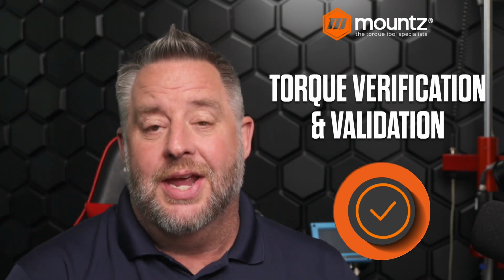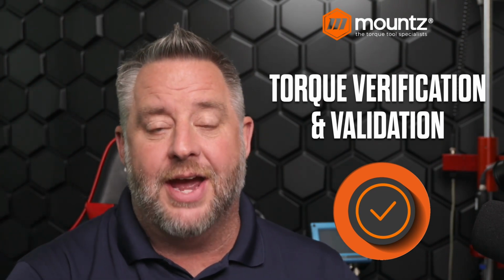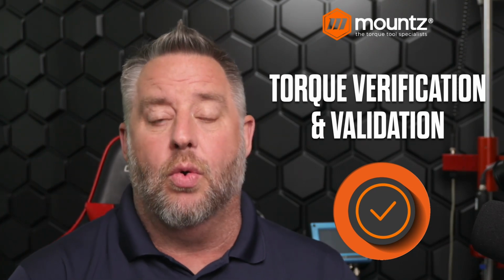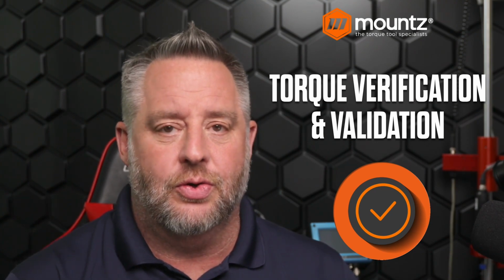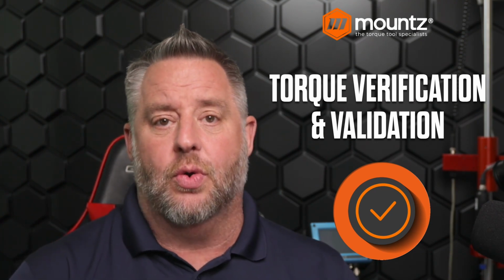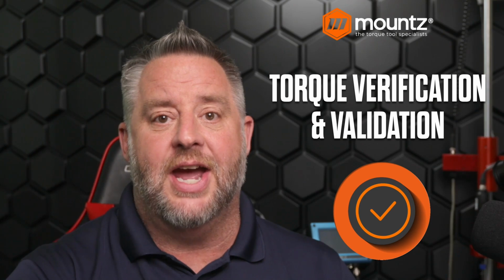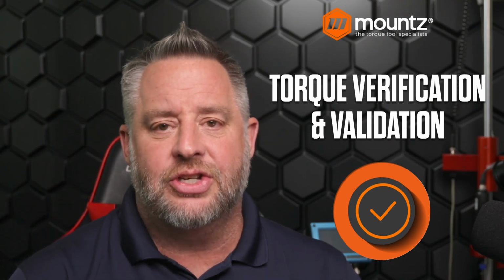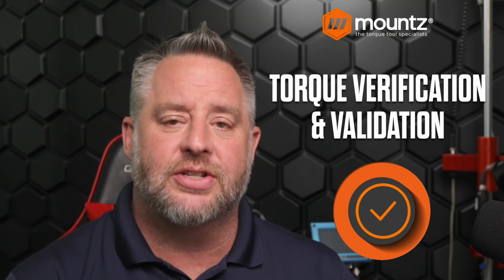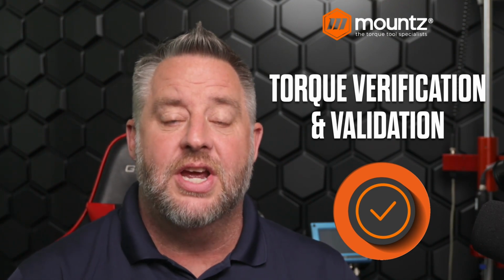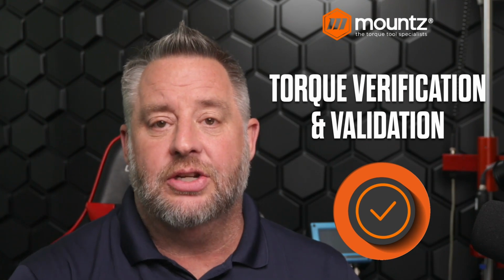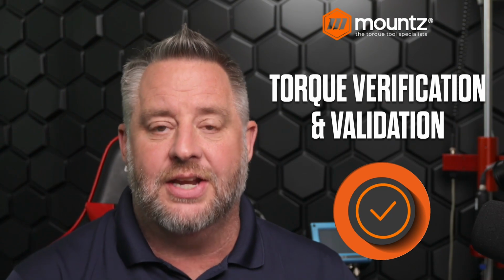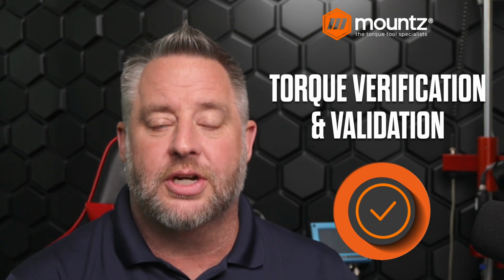Is it a critical type of application? Is this going to cause us to do any type of rework, or are we going to be needing to contact end users or subcontractors that we've had an issue with this tool? And so the torque verification and torque validation process allows us to test a tool actually during the actual assembly process to validate and make sure that it is still within its torque specifications.